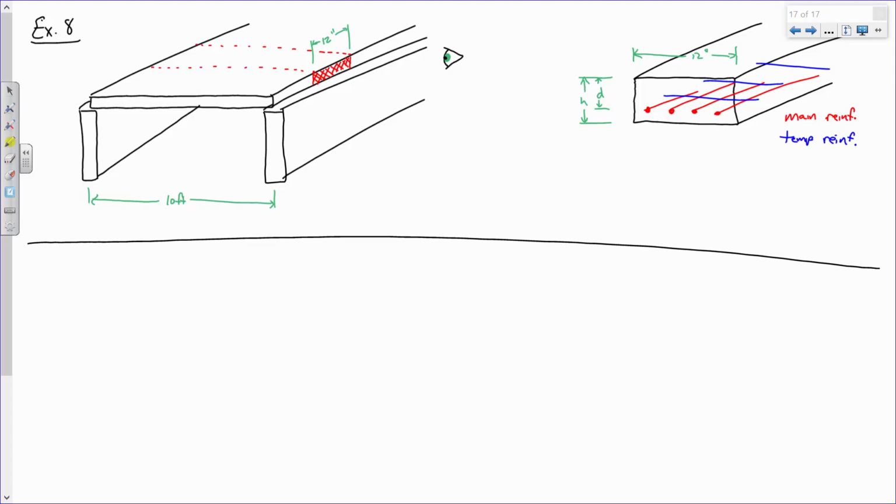If you're okay with that, then let's do this like we have done pretty much any other problem up until now. Our first step is always to compute MU. Okay? So let's go through that. Now, help me out. I have a beam with certain dimensions, B wide, H tall. In this problem, the beam doesn't have any superimposed dead load, but there is its self-weight, right? So what do I do there? I've got to compute the load due to its own self-weight. How do I do that?